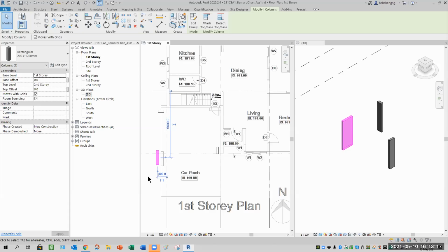Coming up, don't worry. Okay, I know that. So we don't follow the measurement, is it? Because this is 200 by 500, so we don't follow 200 by 500, is it? We just measure by ourselves, seeing how big the column is, then we just write it down in the type properties. Yes, you are right. Of course, if you are using the same drawing file as me, I just follow my steps only.